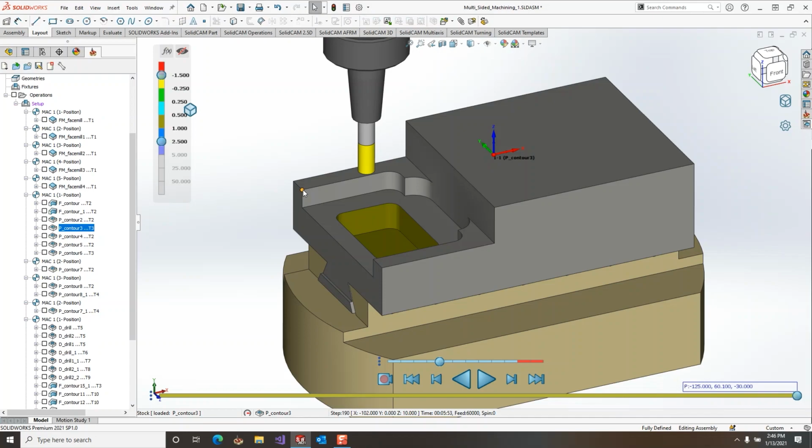If I click on a vertice, we can see that we get a measure in the bottom right hand corner. This is a clickable field, so that way you can copy and paste from this. You can measure vertices, you can measure lines, which give you length, and you can also measure faces. And faces will give you the vector, the distance from the origin, and also the distance from the target.